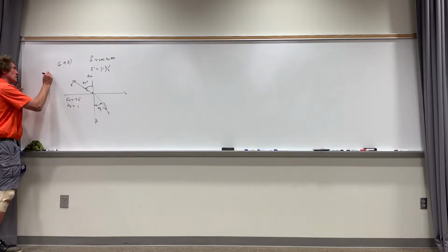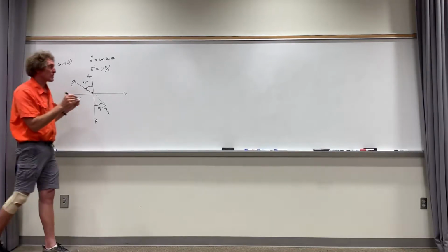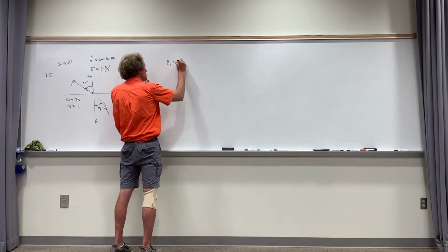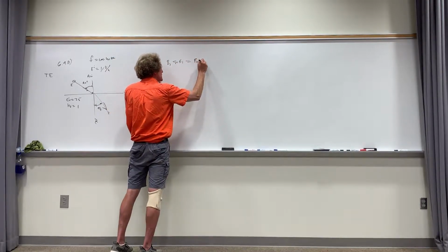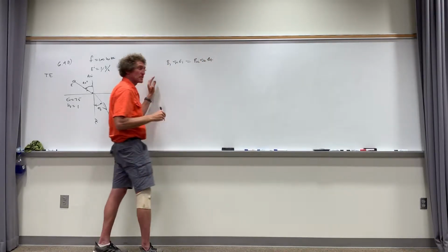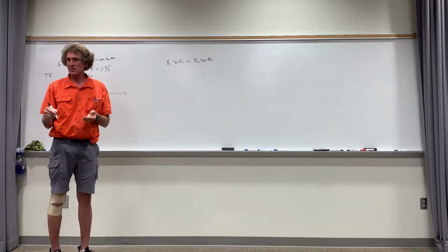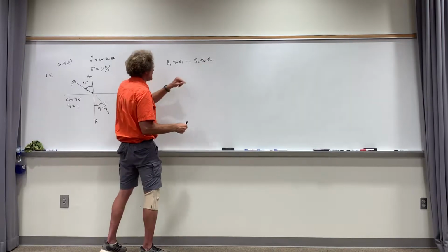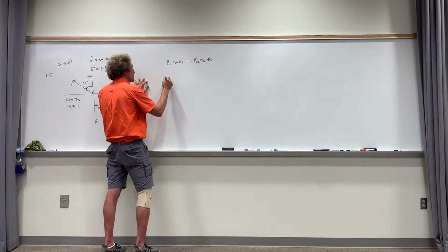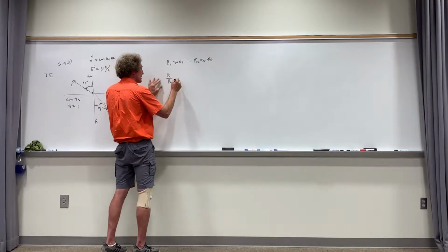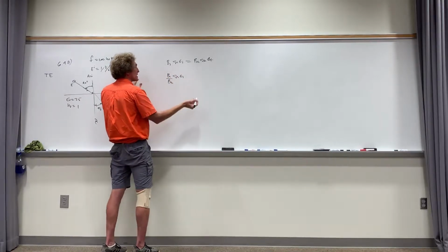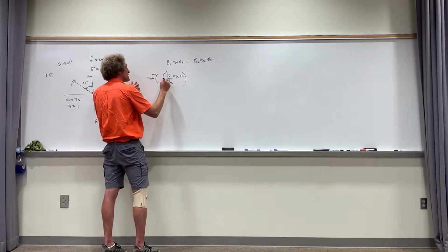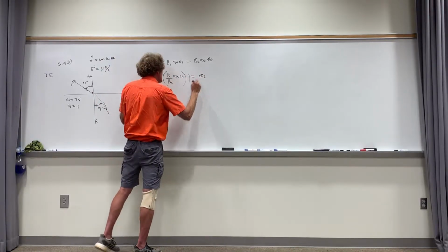So this is a TE mode, right, class? For TE mode, I'm going to go through this. First, we'll use Snell's law. Snell's law says what? Beta 1 times sine of theta incident is equal to beta 2 sine of theta transmitted. Do you agree with me, everyone? Now, in our case, the incident angle is known. We need the transmitted angle. That's this angle. So if we take beta 1 by beta 2 times the sine of the incident angle, and then we take the inverse sine of it, it would be sine minus 1 of this would be actually our theta transmitted.